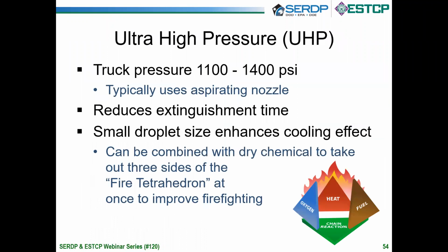So let's look at another technique, ultra high pressure. This is where we're using pressure a little over 1,000 psi, and using an aspirating nozzle. And we look to reduce the extinguishment time. We have just started testing it, so I don't have results today. But this technique can be used in combination with dry chemicals like potassium bicarbonate.